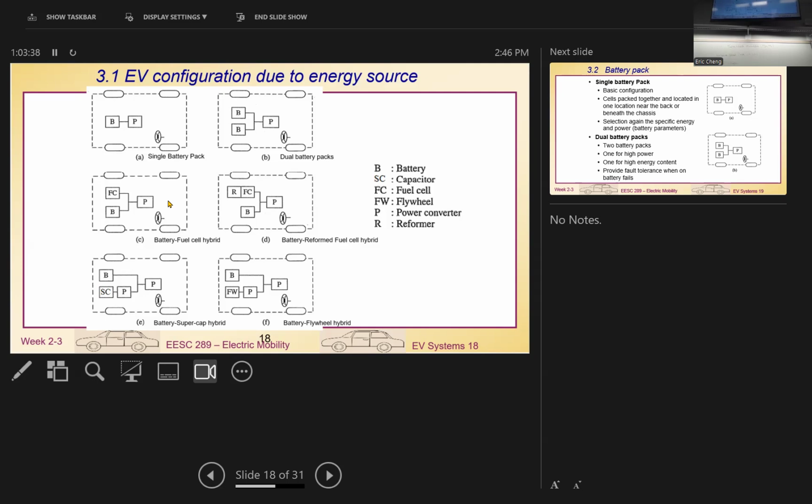Okay, then we do have supercapacitor here so that we can match up the full voltage here. Because it's too expensive, we cannot use too many supercapacitor cells. And also too heavy. Supercapacitor usually will be at least 10 times more expensive than battery and 10 times more heavy than battery. So we just put a little bit in for protection against high current.